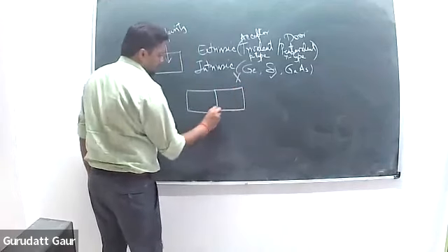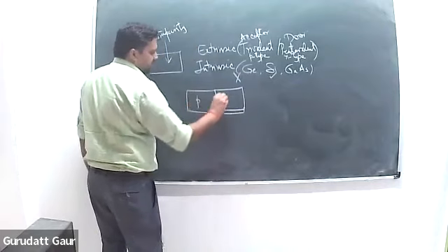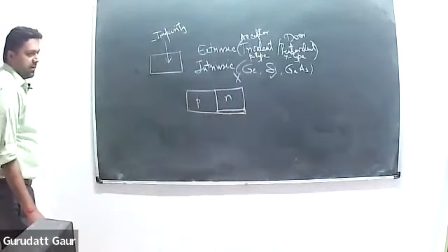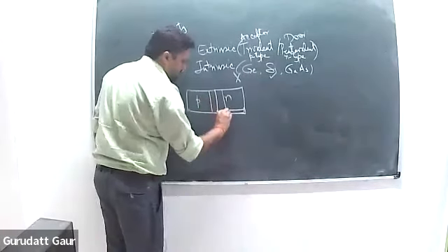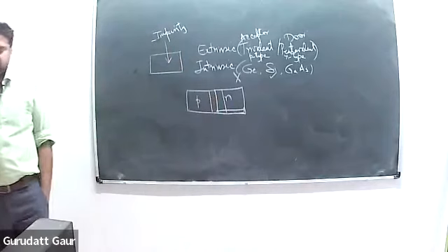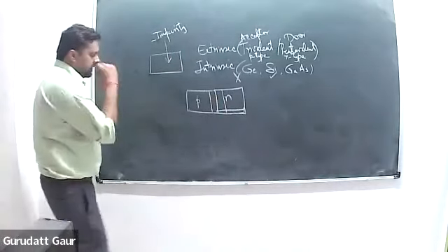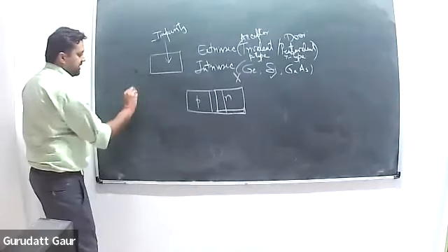So what people did, they chose two different kinds of semiconductor material and put them side by side, and made a junction out of it. This becomes a PN junction diode. And what happens is that a region is created, known as the depletion region, and that also creates a potential barrier between these two electrodes. So this is known as the diode.